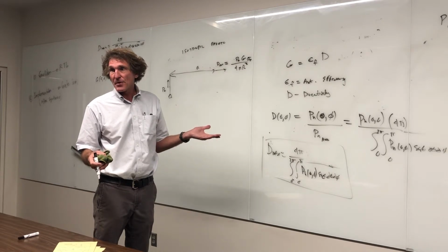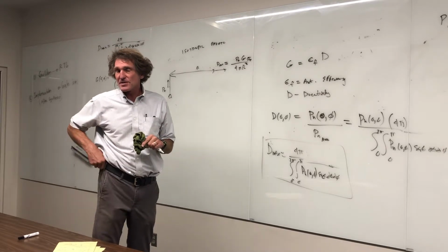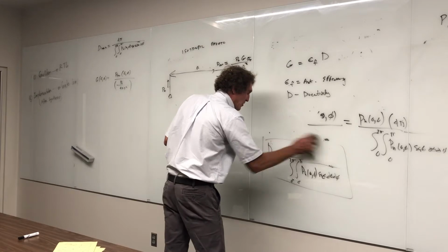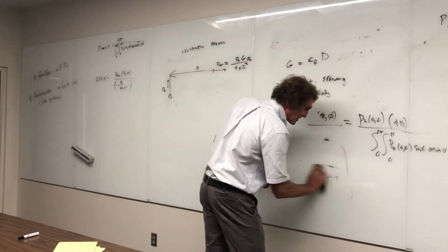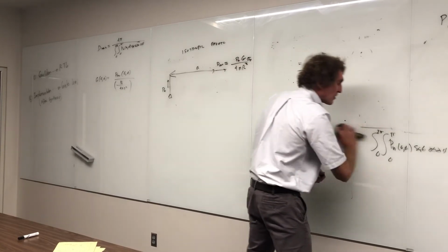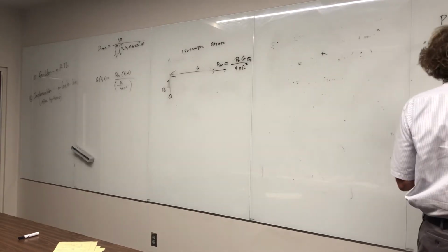Anything above about 30 dB, now you're pushing the limits, now you're talking about some complicated things, usually, and this is a gross generalization, but it's still true. All right, more on this. Now we're going to talk about radiation efficiency. I hope I can have time today to get into actual thin wire antenna, so you can see how we go right from first principles with a thin wire antenna and get all this. I don't know if I will, but I'll try.